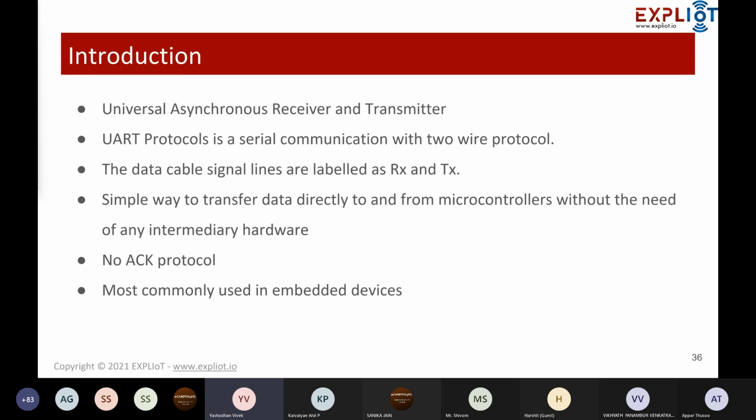So we'll discuss a few things about the UART protocol. I believe we must have gone through those things, but to get into that scenario, let's discuss some key aspects of the UART protocol. A UART communication is sometimes also called a USART, a universal synchronous asynchronous receive transmit, or only UART, universal asynchronous receive transmit. This way we have two-way communication between the transmitter and a receiver, and it is one of the most fundamental protocols. It doesn't expect any kind of acknowledgement from a receiver or transmitter.